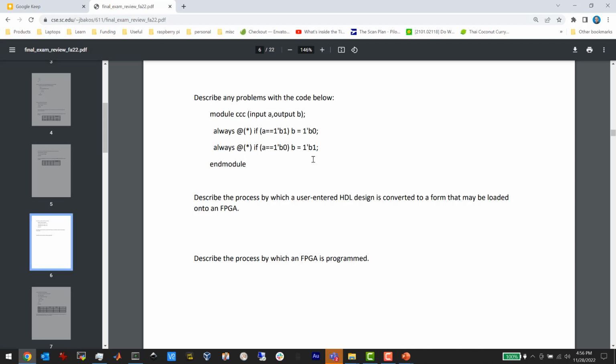But basically, it converts the Verilog to a graph, which is a schematic, which is primitives connected by wires. So whatever your primitives are, gates, flip-flops, adders, hardcore adders, whatever, the synthesis lowers the Verilog, the RTL, register transfer language, down to a schematic netlist. And then the place and route is what converts that, puts that netlist on the FPGA.